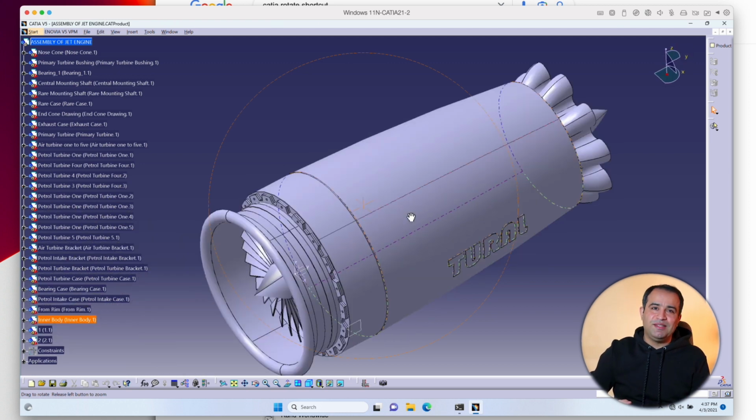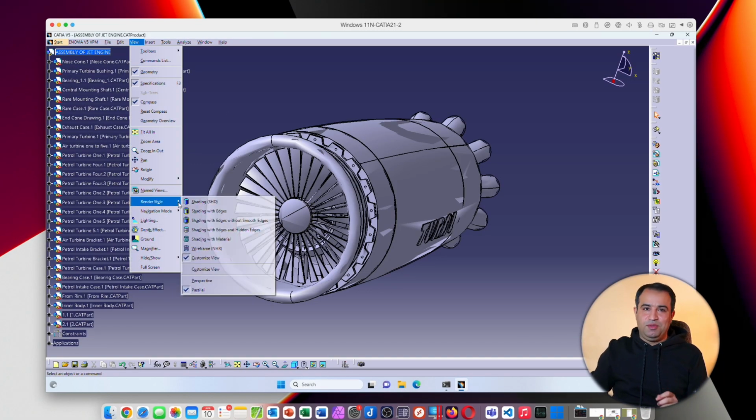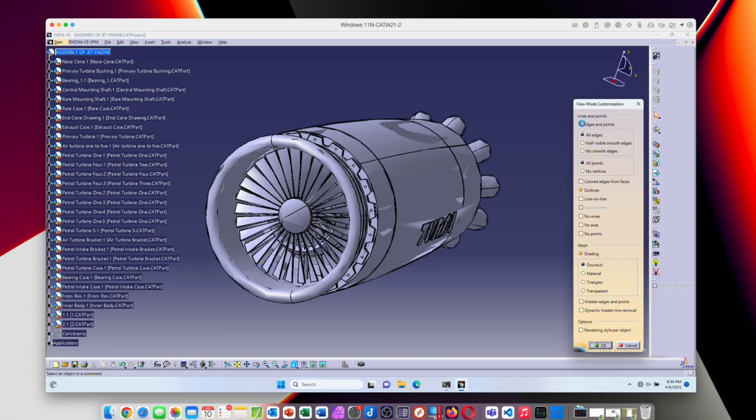This was a surprise since I remember the very good graphical performance from my tests on Abaqus, which uses a graphic engine quite similar to CATIA. After tweaking some settings, I finally started to observe smooth performance on single parts and smaller assemblies. The issue was found to be mostly with rendering edge lines, which I succeeded to address by defining a customized view for the render style.